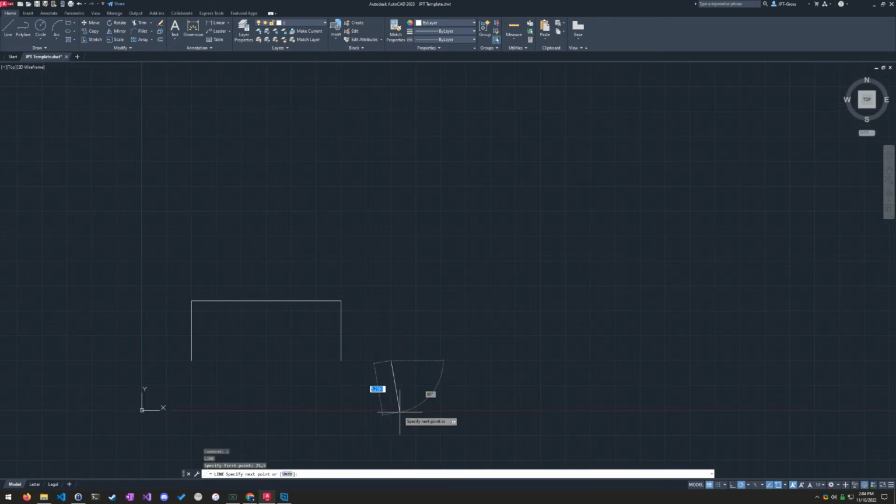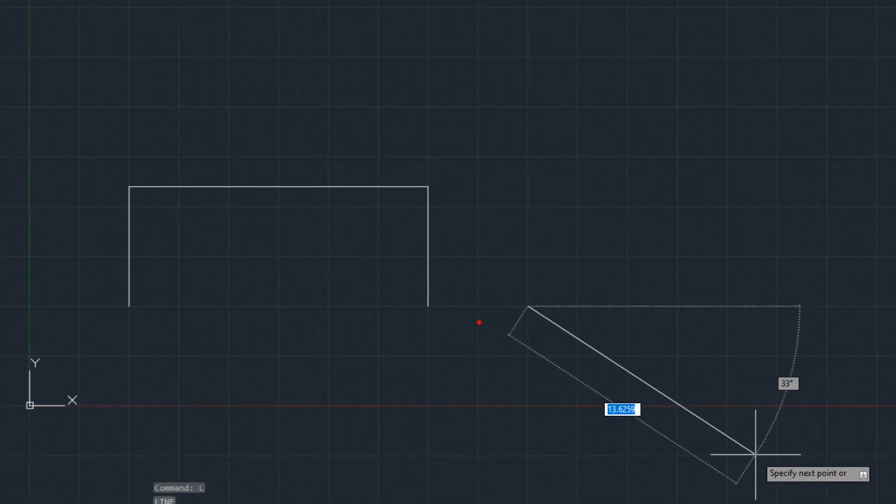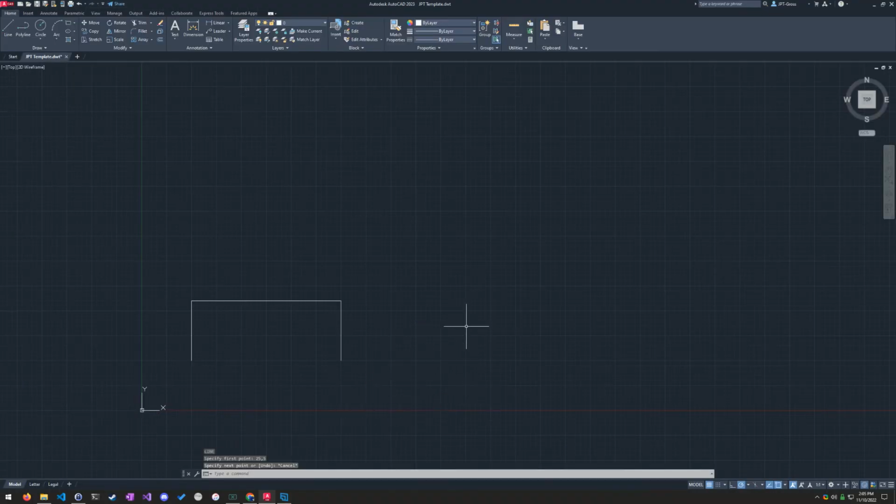And that will put us in the same position up, but much further to the right. That's what the 25 was. Okay. So one more time, L enter, 25, 5, enter. And now shift 3 to get the hashtag or pound sign. And where do we want to go? We want to go 6 units up, but stay in the same position on the X line, but change Y by 6.